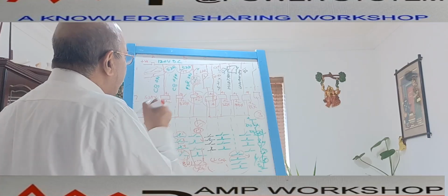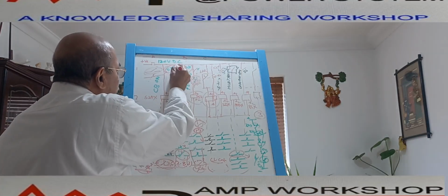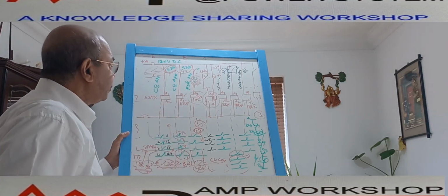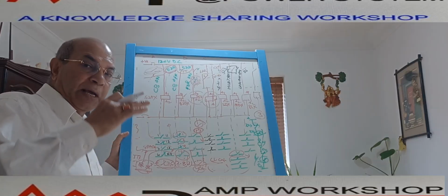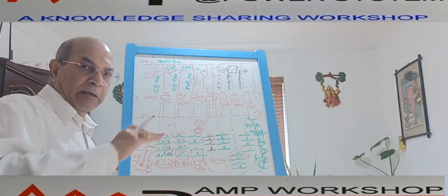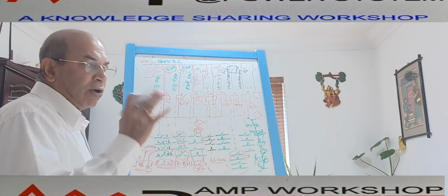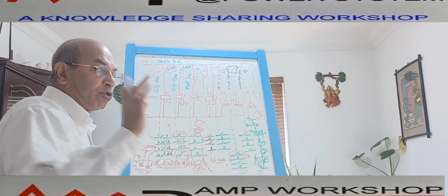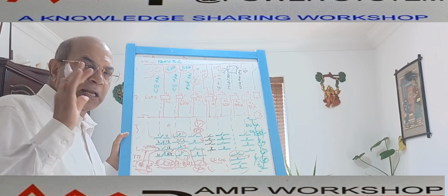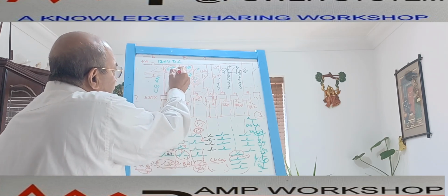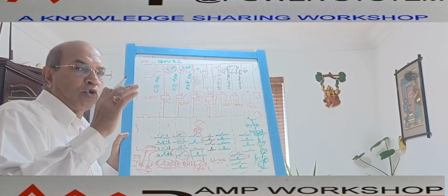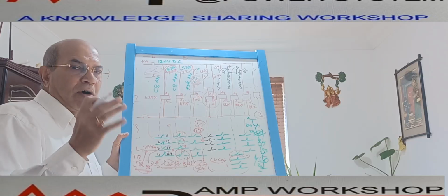Suppose this is another, say a 52A contact, where we are using the breaker auxiliary contact. This breaker auxiliary contact we will be showing in the breaker scheme. When we show the breaker internals in that drawing, this 52A will be shown there. That drawing may be on page number 6, so this may be coming from page number 6, suppose row B, column 2.